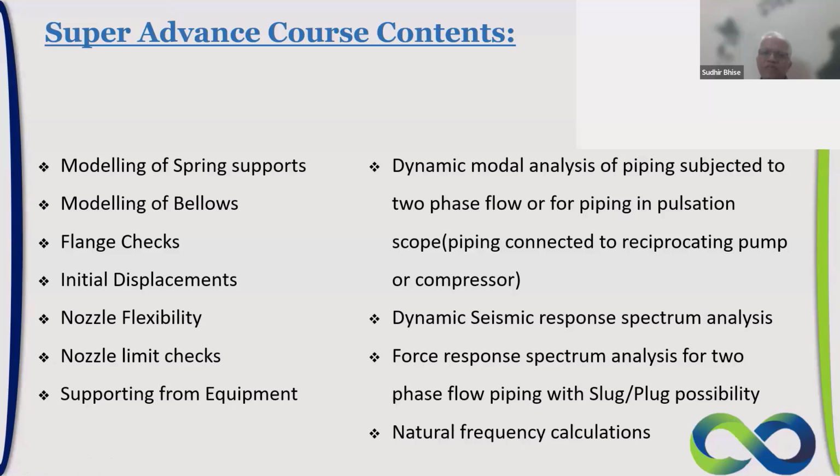For example, natural frequency calculation, then dynamic model analysis for pulsation, then dynamic analysis, seismic response spectrum analysis, force response spectrum analysis for slug and plug applications. So we are going to study such advanced cases also, which are generally not available in the industry for anybody to study. We are going to cover that part also in our Caesar applications.